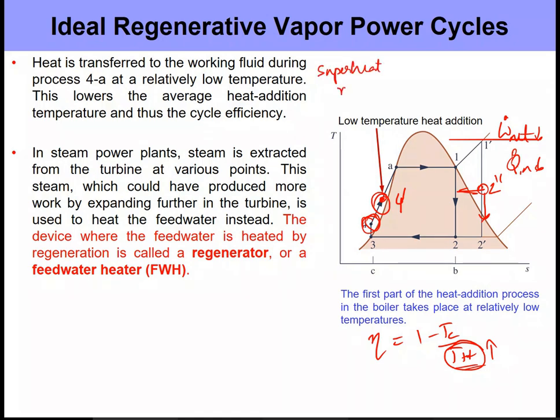So till now, when we were looking at any modification such as superheat, reheat, or even increasing the boiler pressure, in all such cases, we had to increase heat input to achieve higher work output. Okay, both were increasing. And of course, the amount of heat input you had to increase was slightly smaller as compared to the network output you were achieving, simply because efficiency was going up.